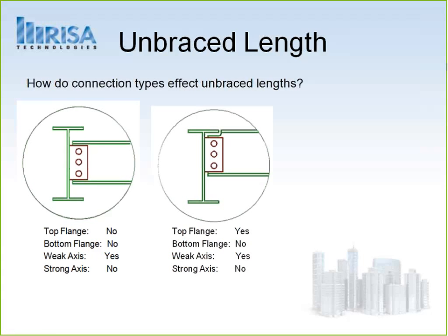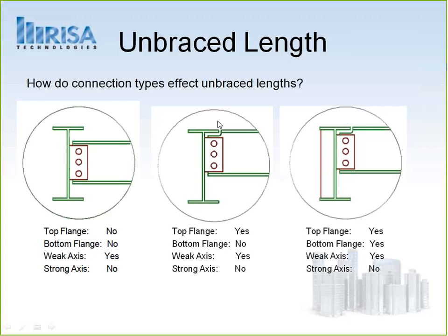Okay, we're going to be bracing that in that connection. The bottom flange is not going to be braced. The weak axis, yes, would be braced in this one, and the strong axis would not be braced, so we would not be bracing it in that direction.